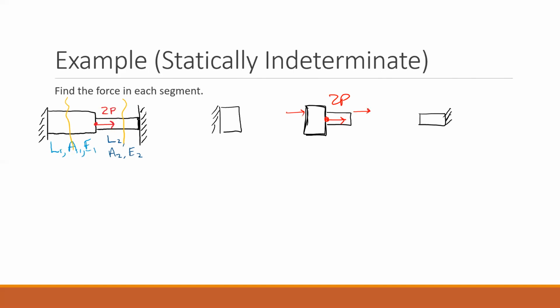And then you can look at this and see that obviously one of those or both of those is wrong, correct? We can't have our force applied and our 2 reactions all pointing in the same direction, at least not in statics. Or if we want it to be in static equilibrium, we can't have this. So you can either draw them all in the positive direction and then later find out that one of them is going to be negative, which would mean that it would be compression.